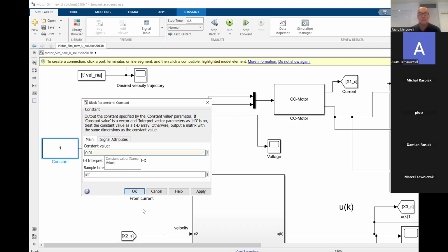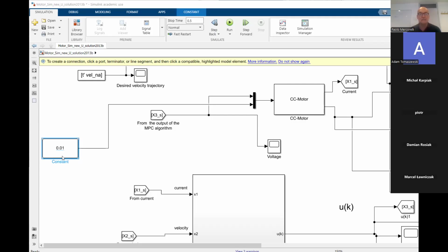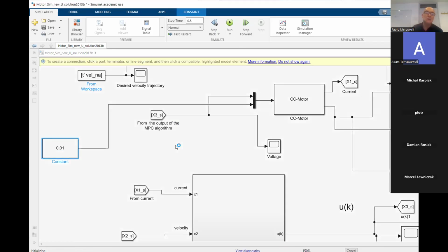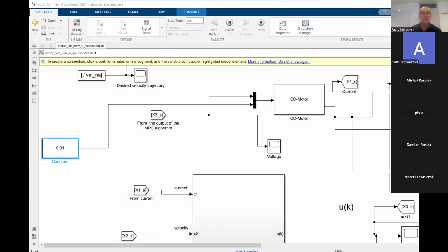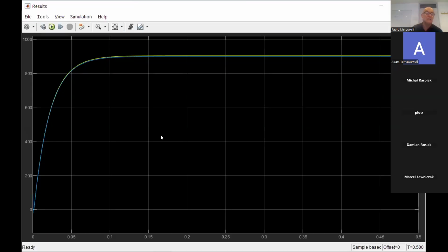Here we have a disturbance which is much less. Let me show you. Now it could be that we are able to control or to reject. Look, almost. Or let me say a little bit better. Yeah, we can see a little bit better. Of course, if I increase RW, I will reject not so good. But in any case, I will reduce the input. This means it's always a compromise.